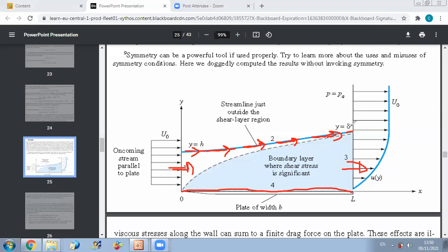And the importance of this is that here at the extremity of your boundary layer, you have that m dot in here is equal to m dot at this level, okay? So here it's just the end of the boundary layer at this point. The point you are considering here is a point of the boundary layer. So we can say that this flux here will be equal to this one, okay?